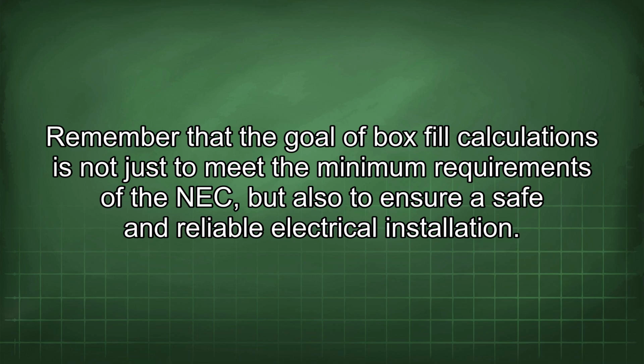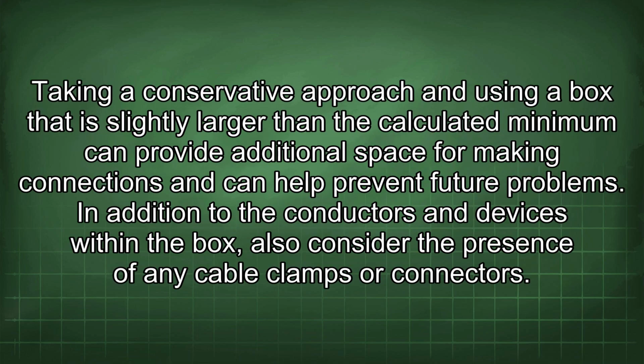Remember that the goal of box fill calculations is not just to meet the minimum requirements of the NEC, but also to ensure a safe and reliable electrical installation. Taking a conservative approach and using a box that is slightly larger than the calculated minimum can provide additional space for making connections and can help prevent future problems.